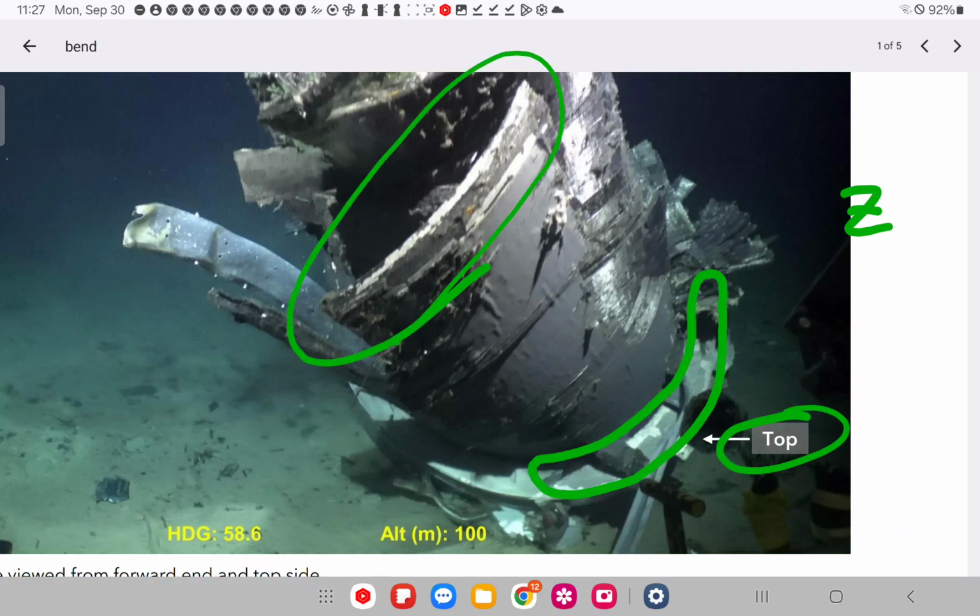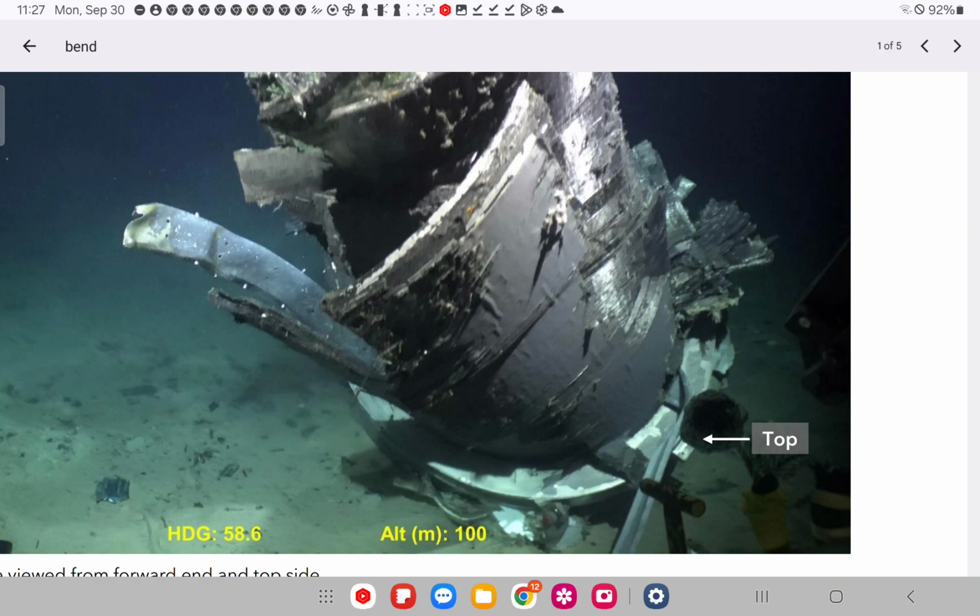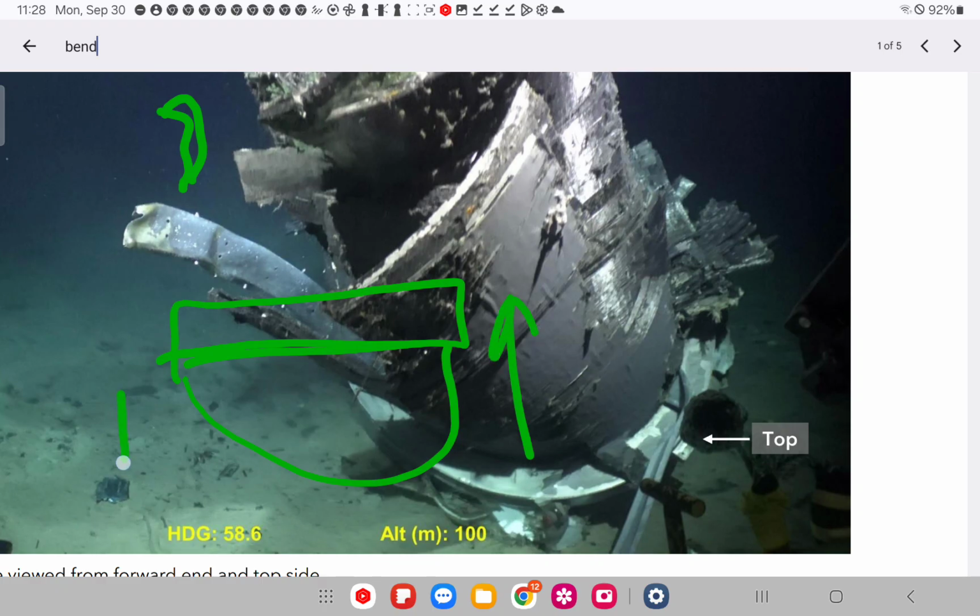This is where the interface ring would have sat, would have seated right there. Interface ring would have seated on this. And you don't see it seated anymore. So it didn't just go directly in. So here's the end cap with the interface ring. And upon this buckle here, that one I showed you, this just didn't go straight in. It didn't do that because it's no longer here. It didn't buckle it, didn't fracture there. So it rotated off of there first, with that being our starting point, the buckling point.